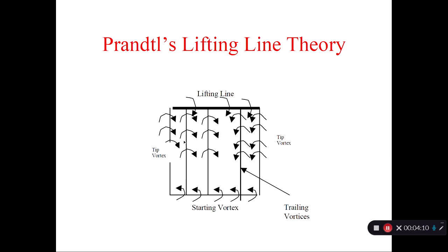These are trailing vortices that are bringing circulation. When they are coming towards it, think of it as a right-hand screw rule. Depending on which way you are turning the screwdriver, you are moving either forward. So that's what's happening. Circulation is being brought. If you're spinning the opposite way, you're moving backwards. Circulation is being removed. So you're adding circulation, you are removing circulation. By the way, if you have a flap or something you're deflecting here, remember locally the camber line will change a lot. So you'll get a huge amount of extra lift. Therefore, this vortex will be very, very strong, highly visible.